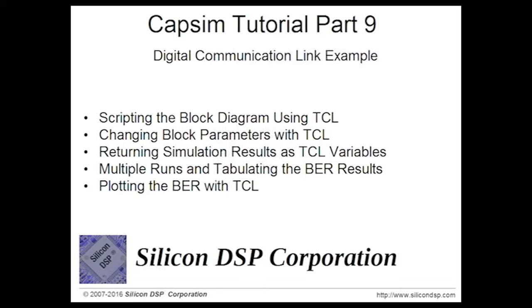In order to use the Tickle script in the graphics mode, you open Capsim by typing on the command line ./capsim -c. So the -c option allows you to open Capsim with both the graphical and also Tickle scripting capability. In the window that you observe, this is actually the Tickle script that you see, and that's the Tickle prompt. In fact, one Tickle command is clear. That will clear the screen.